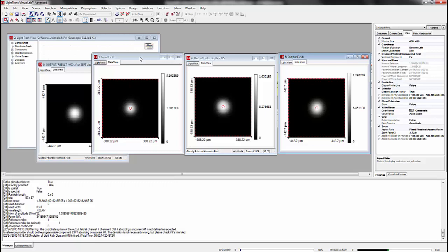The input power was 102 megawatts. Halfway through the sample it dropped, and at the output it was down to 34 megawatts. So this is not a perfect optical limiter, but it demonstrates optical limiting. So now I'm going to close this program. We've finished with this example.